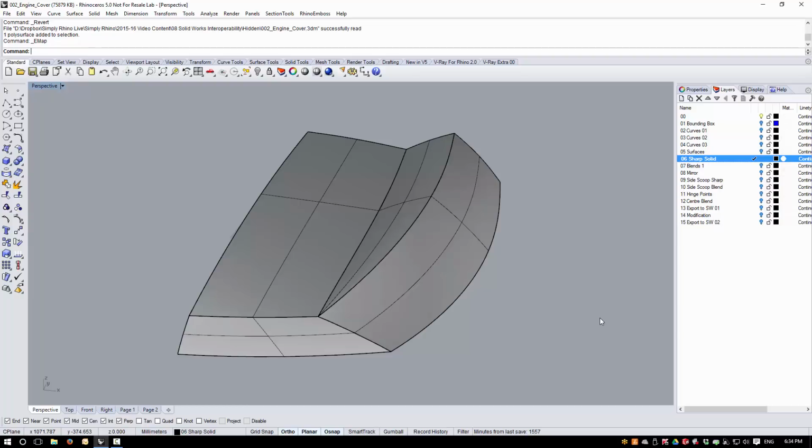Here I have a closed poly surface or solid, and I'm going to use the solid blend edge tool. Because of the fact that we have 4 edges that all converge to a point, and that one of these edges will have a substantially larger blend than the others, then the geometry isn't ideal. This will result in the solid blend edge tool failing to complete, but we can use the surfaces that the tool does create as a starting point to build the troublesome corner manually.